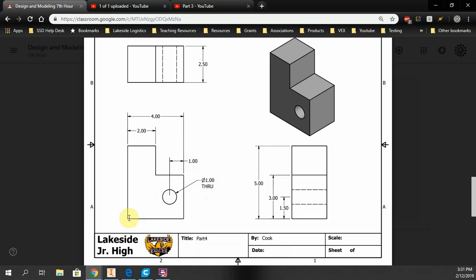And so if I start here, I can see that from here to this point is 4 inches. Going up, it's a total of 3 inches. So if I look at my heights over in my right side view, it goes up 3 inches. Now if I'm going from the right to the left, 4 inches minus 2 inches is once again 2 inches. So this line is going to be 2 inches. I go up, 5 minus 3 is 2 inches, so this is going to be 2 inches, and then this is labeled as 2 inches, and then all the way back down again, so from this point to here is going to be 5 inches.